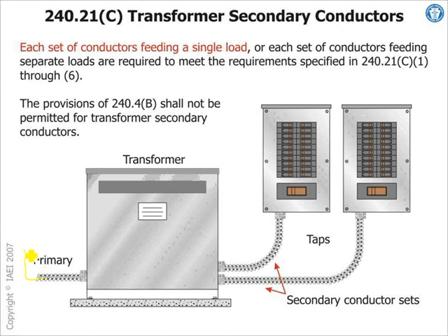You're looking at a circuit breaker coming in here, right? That's where we take out the transformer here. Now, the first tap that I'm going to talk about is the tap right here. How far? Because this is a tap, right? From here to here, there's no overcurrent protection device. Let's talk about the secondary conductors. Secondary conductors 10 feet. Let's say this is 10 feet or more. Are you guys with me? So the secondary conductors are 10 feet or more.